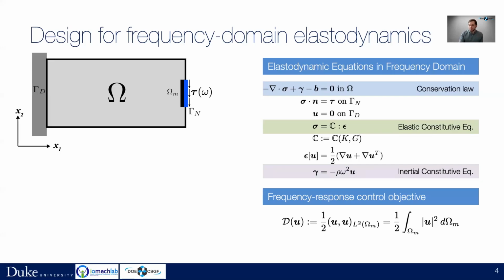We will measure the response using an L2 norm of the displacements in a measured subdomain. Essentially, you can think of it as the squared amplitude of vibration that we try to minimize in a certain region of the domain.